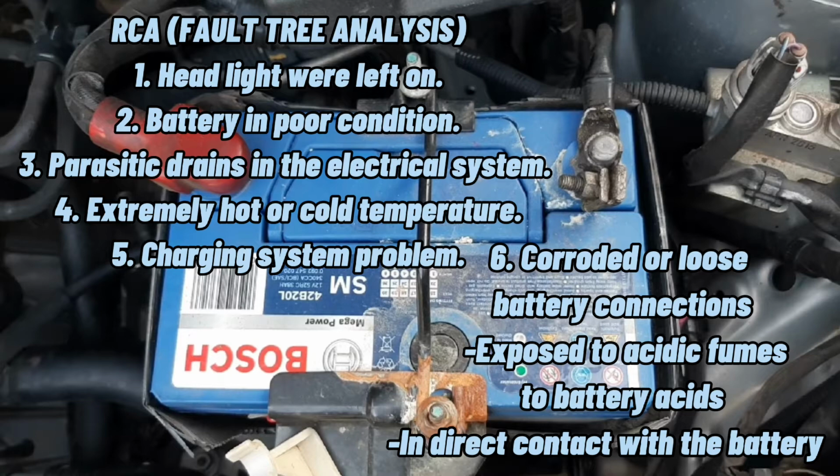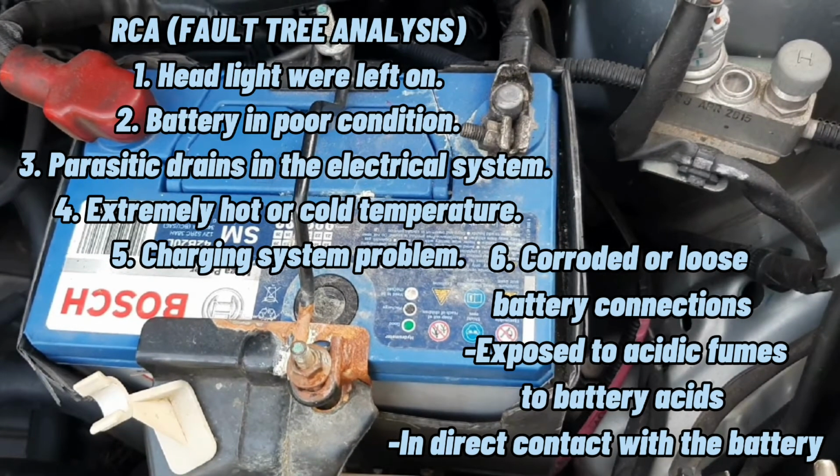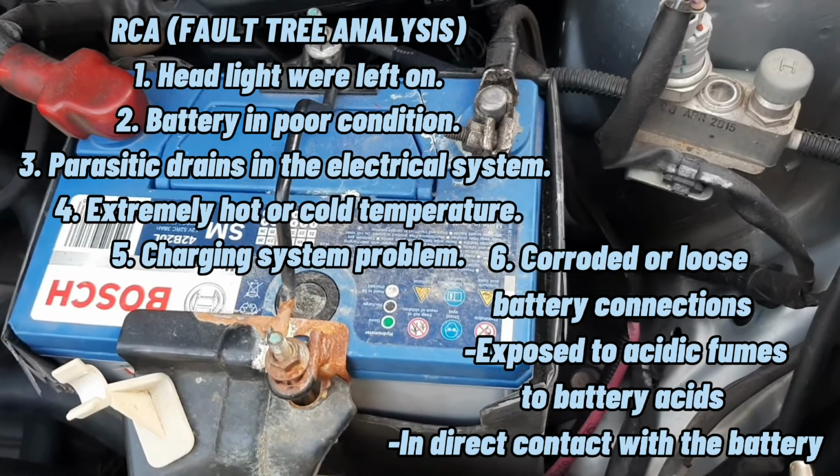Based on the RCA fault tree analysis, there are many possible problems that cause the battery to die, which are the headlight or dome light being left on, the battery being in weak or poor condition, the corroded or loose battery connections, the parasitic drains in the electrical system, the extremely hot or cold temperature, and the charging system problem.